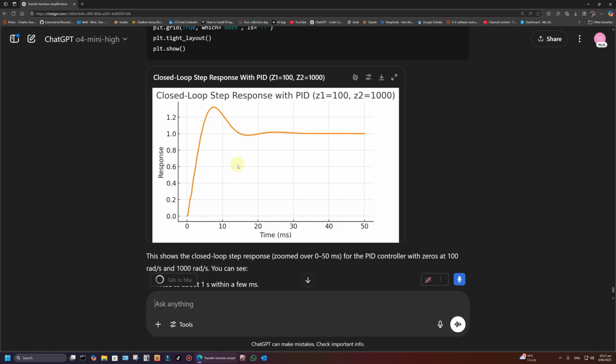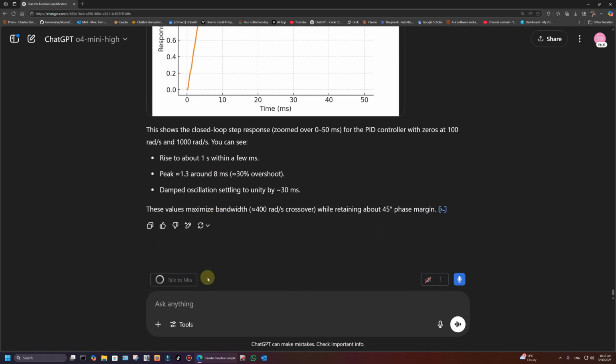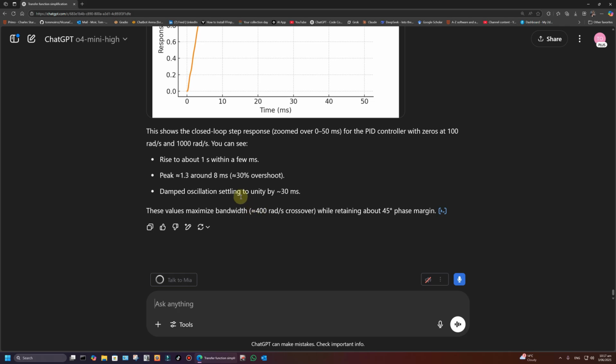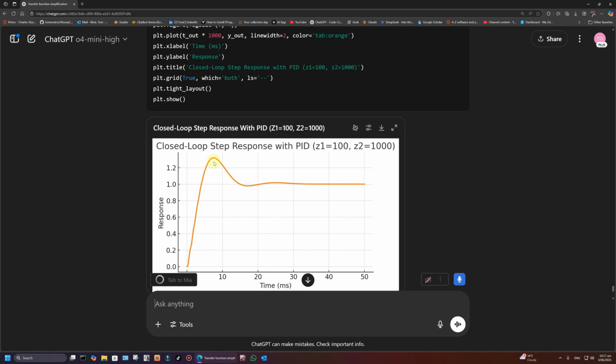Well, marks out of 10. It's not bad. It's not bad. And what's the bandwidth as it's produced? Oh, the maximum bandwidth of 400 radians. What's that? About 80 hertz or something like that. Yeah, I suppose it's not bad. What did I get? I'm trying to look on my. I can't see it. Yeah, it's not too bad. Quite reasonably fast. The overshoot's a bit on the big side.